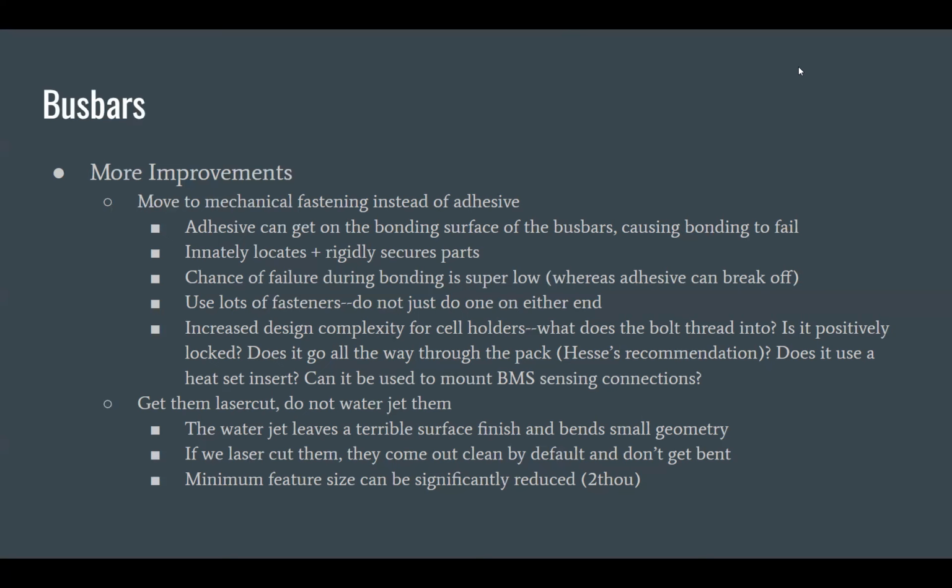And then once you have the idea of what that's going to look like, you do a first pass going through and saying, okay, based on our knowledge of all the other things, the sensing connections and the BMS mounting and all that, how do we tweak and modify those existing large architecture designs to fit in and solve these problems? And if something is a major issue, you might have to say, for that reason, I have to go back and restart my larger cell configuration within a segment.